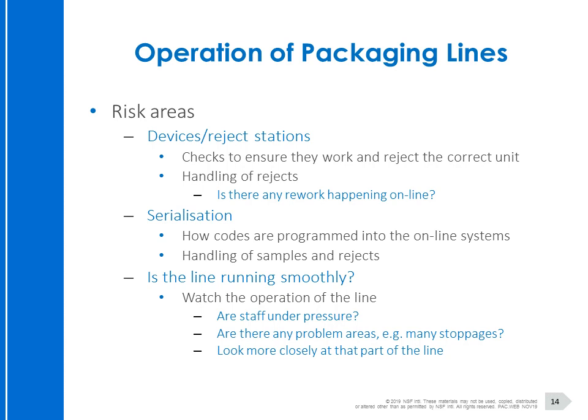But what's really important is that you look and check, and perhaps ask the staff if they could perform some checks to prove that it is picking up errors, and the unit is working correctly. And also, most importantly, that it's actually rejecting the correct item. So it might identify an error, but making sure that it actually rejects that unit that has the error is very important.